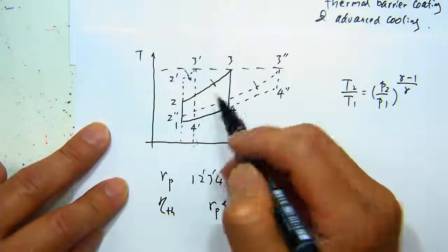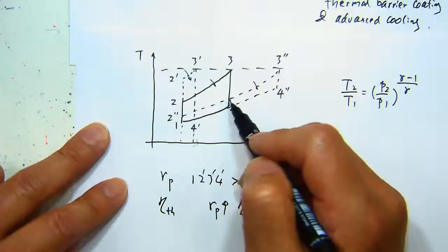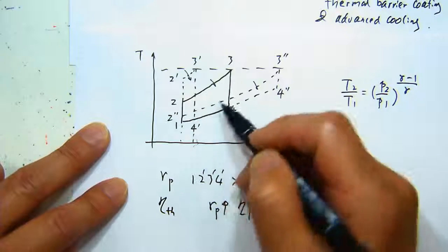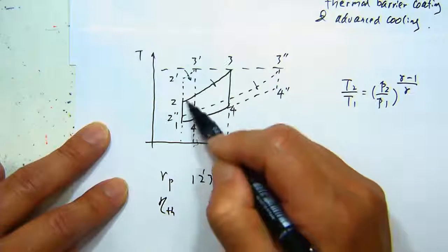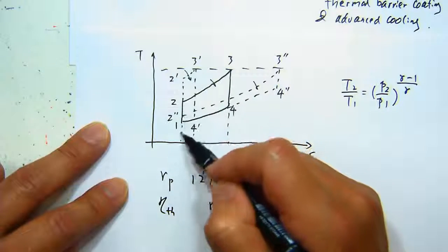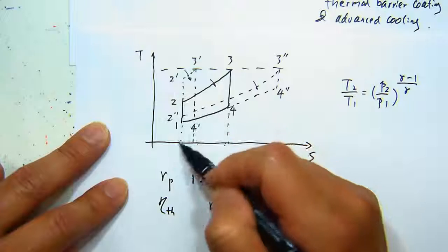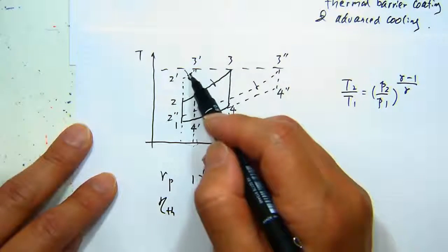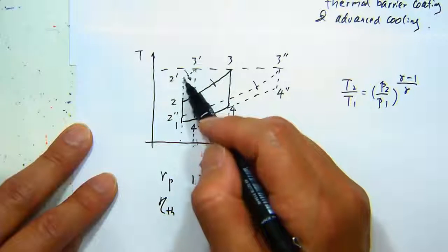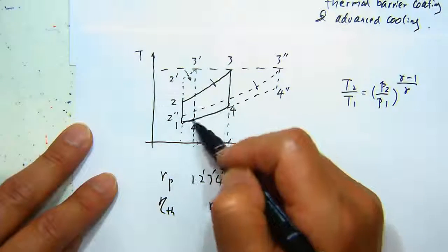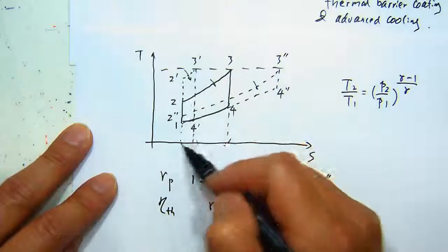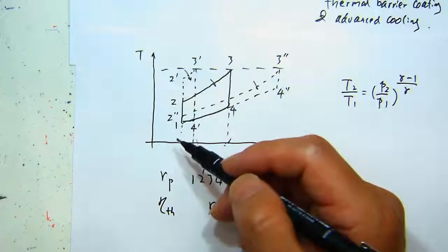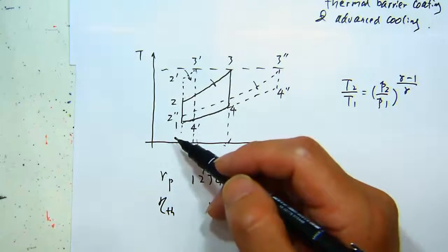That's the work, and the efficiency you can directly tell from the fraction of this work over the total area underneath this curve, which corresponds to this area. So you should be able to tell for the single prime case, the work corresponds to this much, and the total area is this much. So the heat being rejected accounts for a smaller fraction in the total.